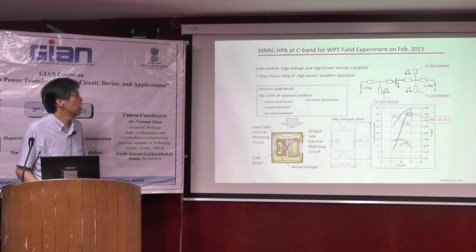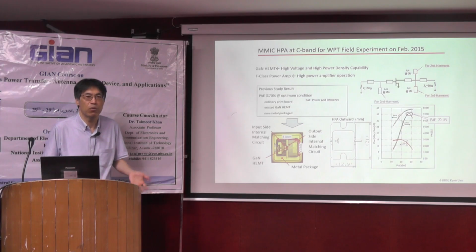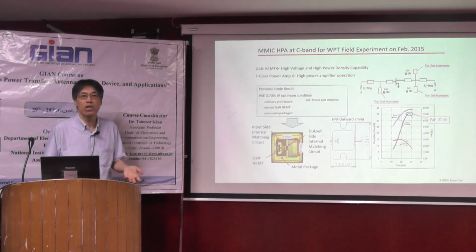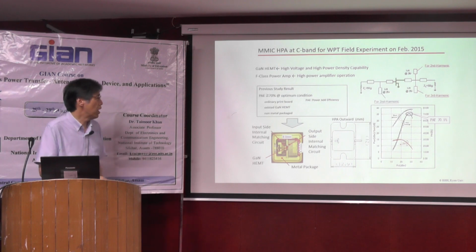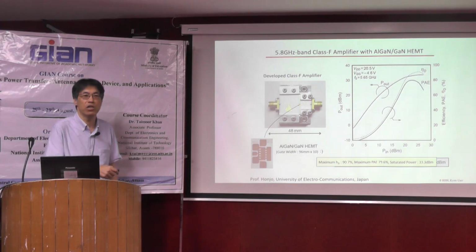So, if possible, you should use this class F amplifier mainly for wireless power transfer, because at the beginning of today's talk, I showed you the recommendation and requirements for wireless power transfer. We don't need any modulation for the microwave because we use a carrier only. So I explain again and again, we add a resonator circuit here.